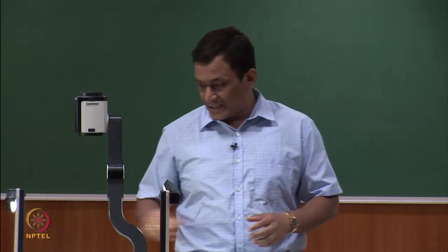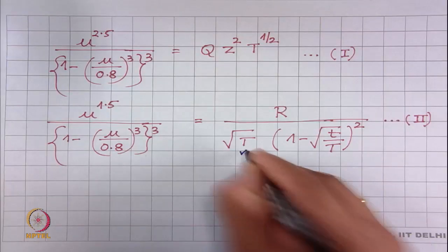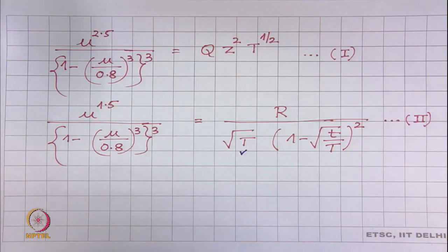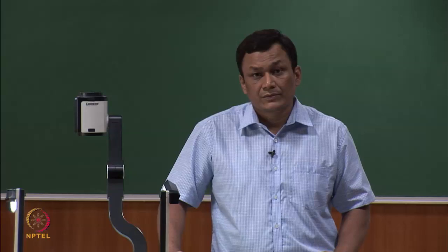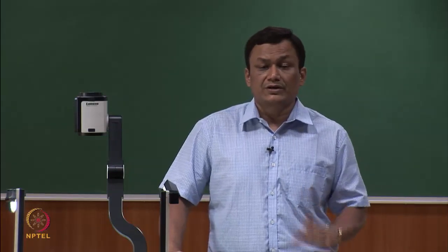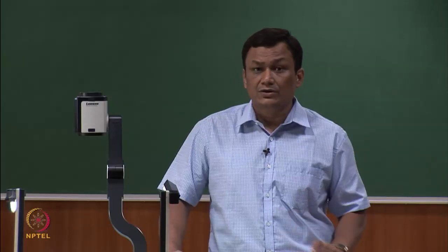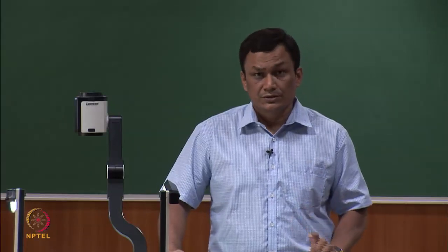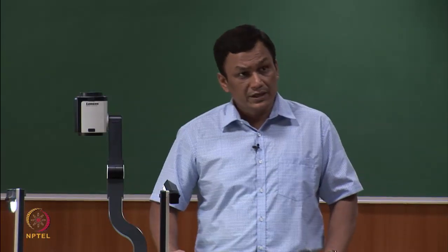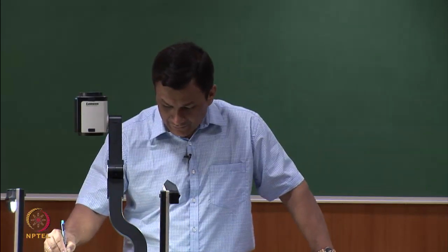So, capital T is generally known before production of yarn. Yes, which fiber I have to use, whether it is cotton or it is polyester or it is viscose. If it is cotton, then it is long staple cotton or short staple cotton, and what is its fineness. This information is also known prior to yarn manufacturing. That means, small t is also known.